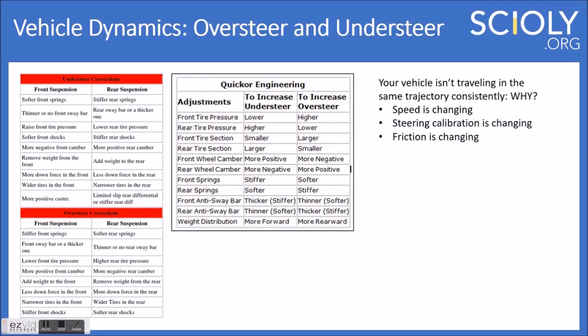And that would change because the battery was being drained over time after each run. So you would start to see these differences. So you keep trying to recalibrate your caliper or the steering, but that wasn't even the problem. The real problem was the speed was changing. So that's something to look out for. That was due to understeer in that scenario.